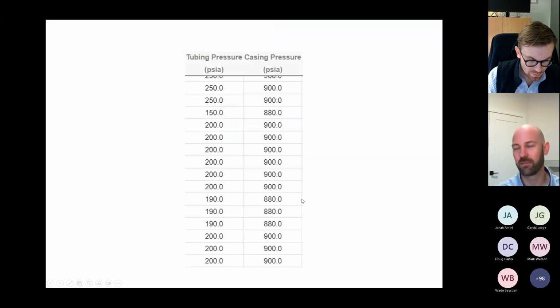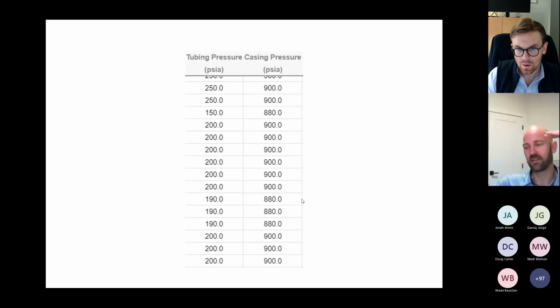So something really minor as well is using different pressure sources to calculate bottom hole pressures. If we're flowing up the tubing and we have a tubing head pressure, we can of course use that tubing head pressure to calculate the bottom hole pressure, right? But what if we're flowing up the tubing, but we want to use the quiet side pressure, meaning the casing or the annulus, to be the pressure source to do the bottom hole calculation? That's something that we can't do at this moment, but it's going to be coming.